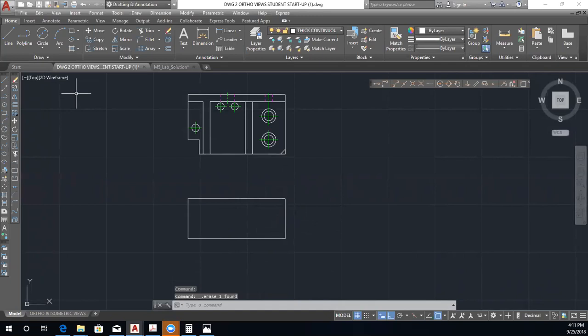All right, and then we will draw the top left, this whole portion right here. It's easy by the front view: we go down by 0.8, and then we'll go to the right, 0.2 plus 0.6, which will be 0.8, enter, and then go up, escape.